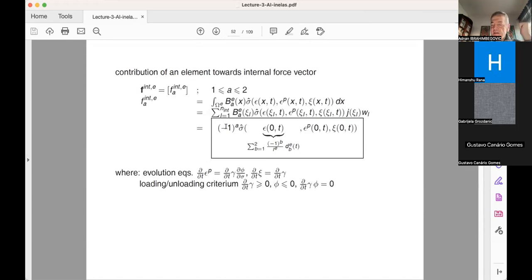So this is really very significant saying for plastic behavior, because that would imply simply that the plastic deformation and hardening variable are needed nowhere else in terms of this element, but at the Gauss point. That's the only place where we need the stress, and for the computational stress, we need this variable. So that reduces the storage of these variables very significantly.